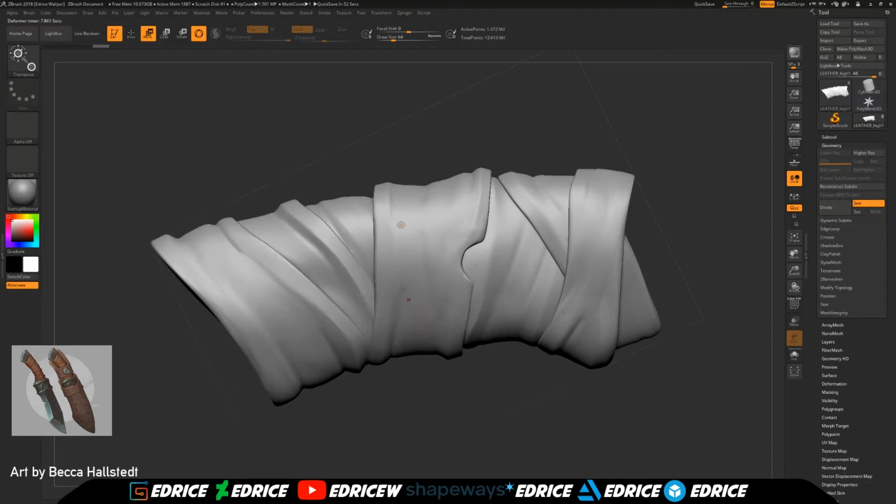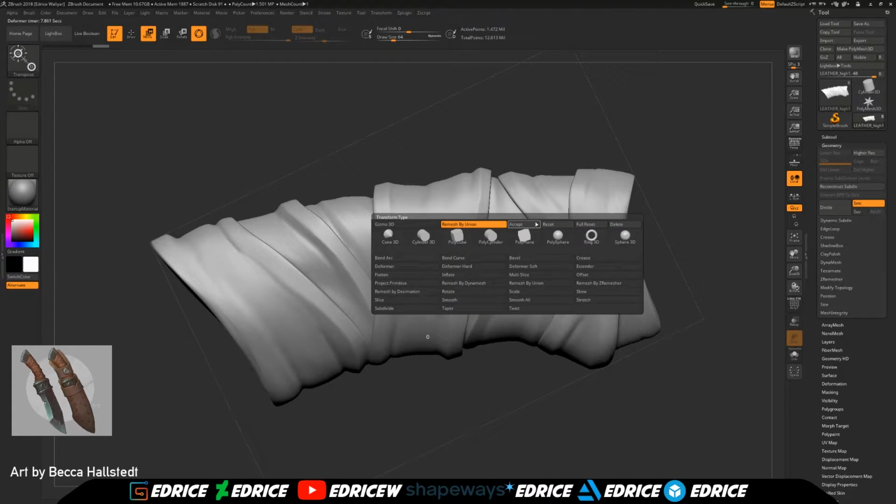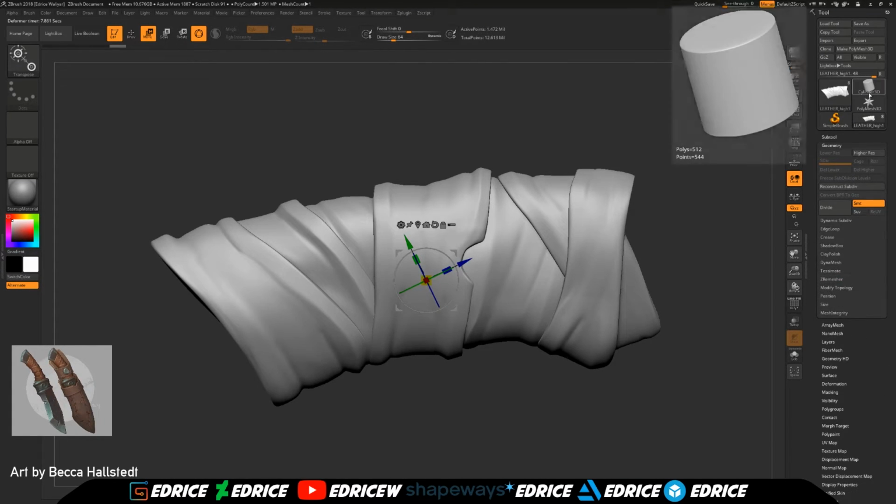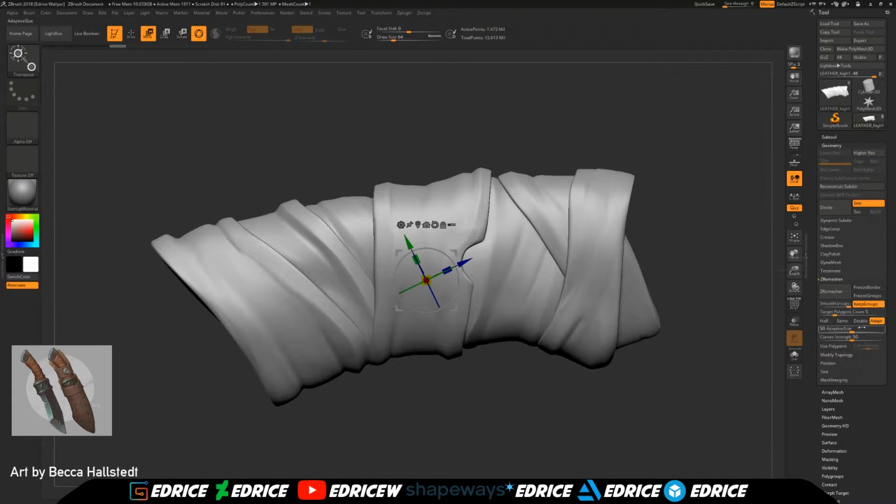And now we're going to move to the lever strap, and here ZBrush crashed on me, so we're going to do it twice. But essentially we're going to ZRemesh it. So we're going to hit ZRemesh, we're going to hit our target of 0.15, and then we are going to turn down the adaptive size to 30.